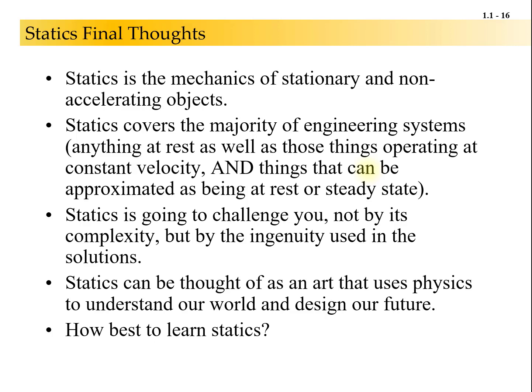Myself being a structural engineer, a branch of civil, I do building design. We do that all the time with earthquakes, right? Earthquakes are a dynamic load. It's an acceleration. It's a ground acceleration. And what we usually do is think about the impact. We turn that into an equivalent lateral force, which is like an impact load, if you will, on the structure. And then we use statics because it's easier.